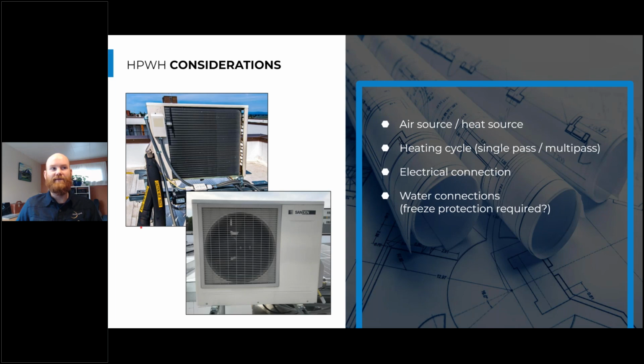The hot water pipe's going to have heat going into it. The cold water pipe's going to be pulling from the city main, typically around 50 degrees. But as soon as that process stops, there's not going to be heat or flow through that piping anymore, so there's potential for freezing, and we want to be proactive about that.